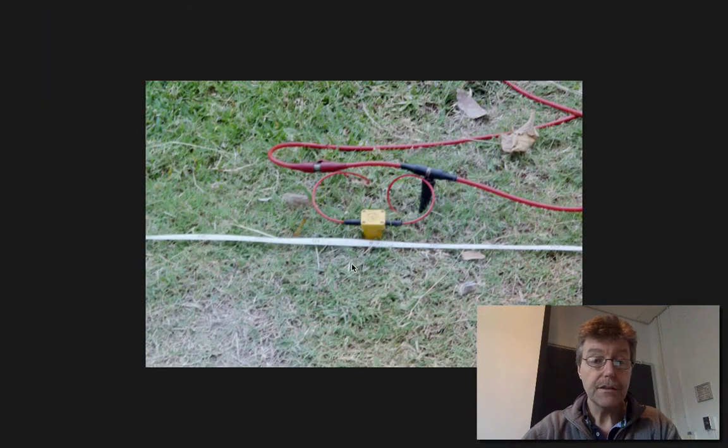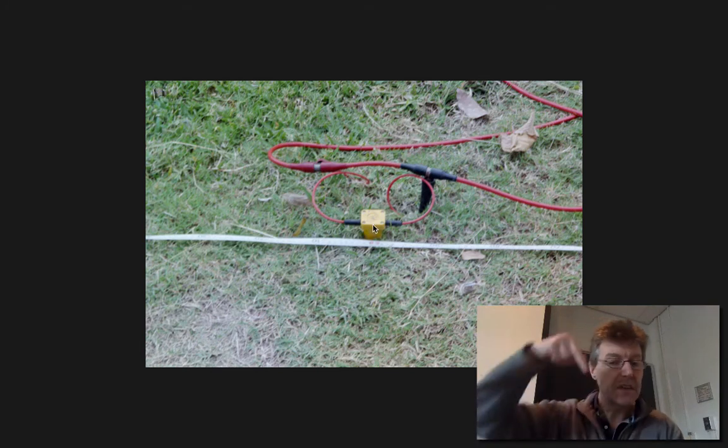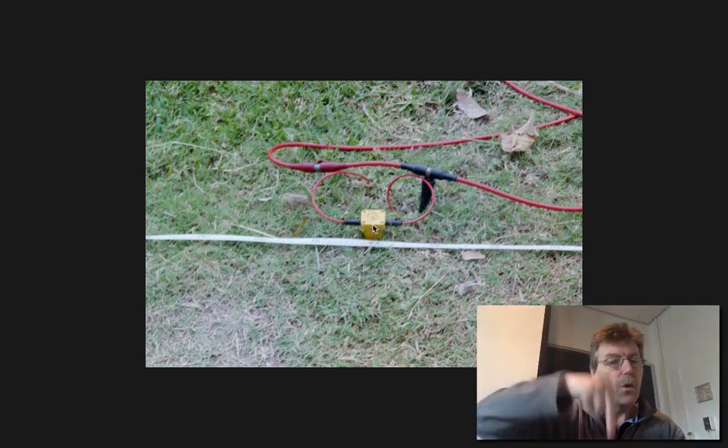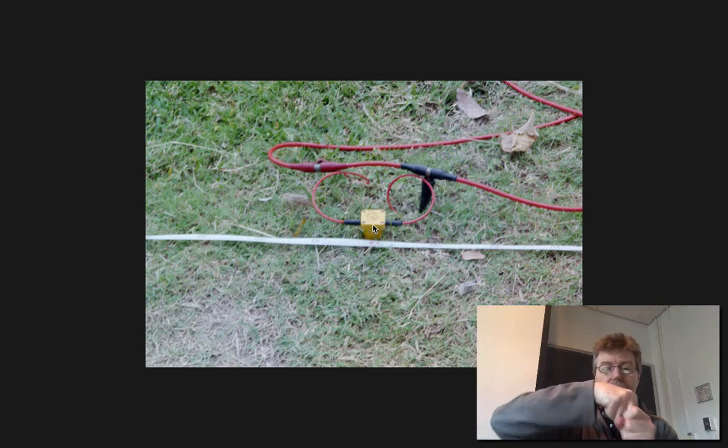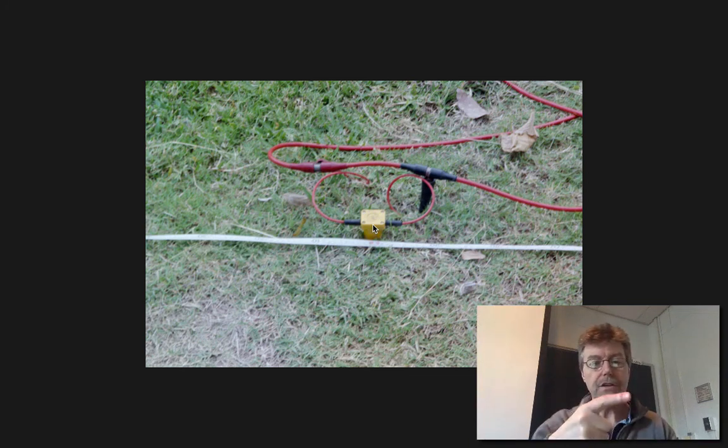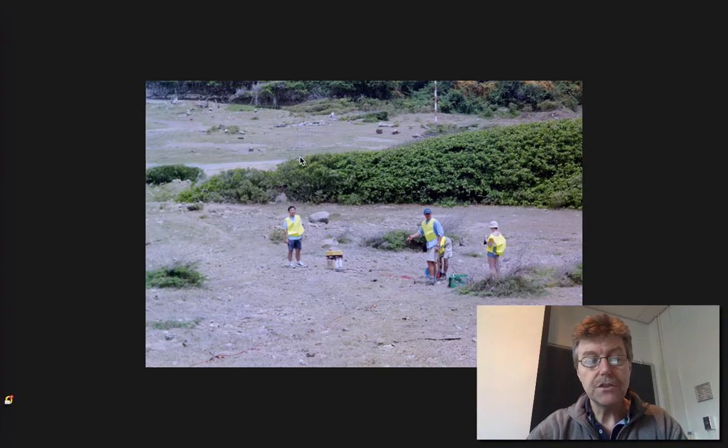Again, part of this. This is a geophone, physically stuck a spike into the ground, probably a one-component geophone. It just measures when it starts to vibrate, not measuring whether the direction is horizontally in the two directions or vertically. It's attached onto this overall cable just by clipping it onto this cable. So this cable will run a couple of 100 meters and will take maybe a dozen of these geophones.